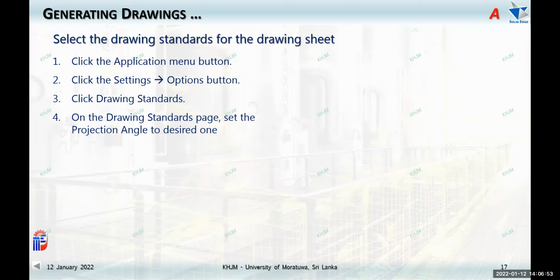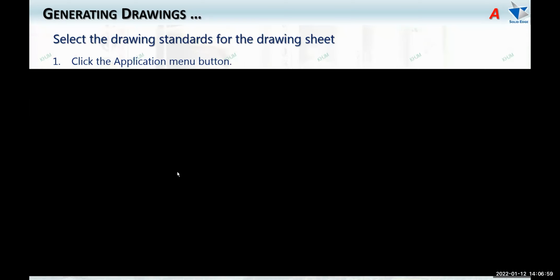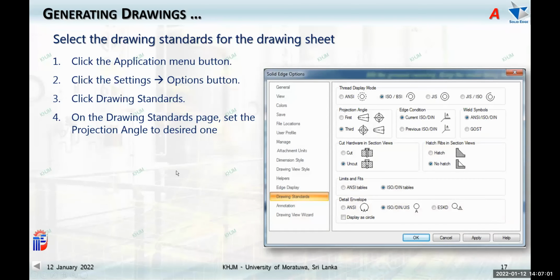The center lines will appear at the same time, or maybe the hidden lines likewise. So this is the settings window. The standard view options are available. You can decide on various options available. And you can see there the first angle and the third angle, I can choose.